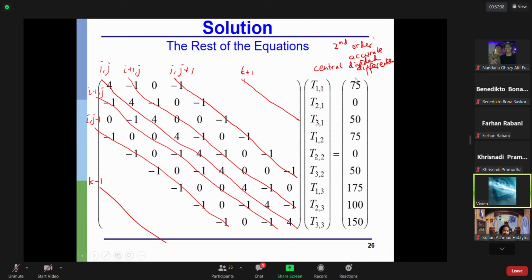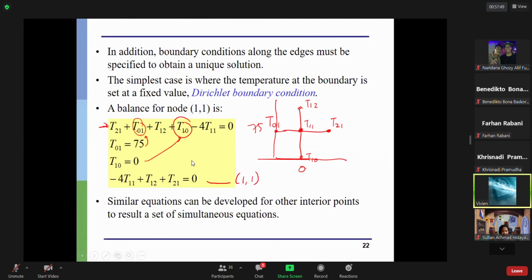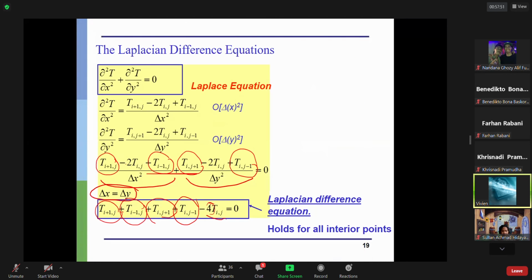Now you can also, for example, apply a higher order accurate scheme, for example, more than second order. For example, we want to apply a fourth order central divided difference. So of course you can just substitute the equation here with the fourth order. When you increase the level of accuracy, you might need to include more neighboring cells. So when you use the fourth order difference scheme, it might be that you need the Ti plus 2 point and Ti minus 2. So this is for fourth order.